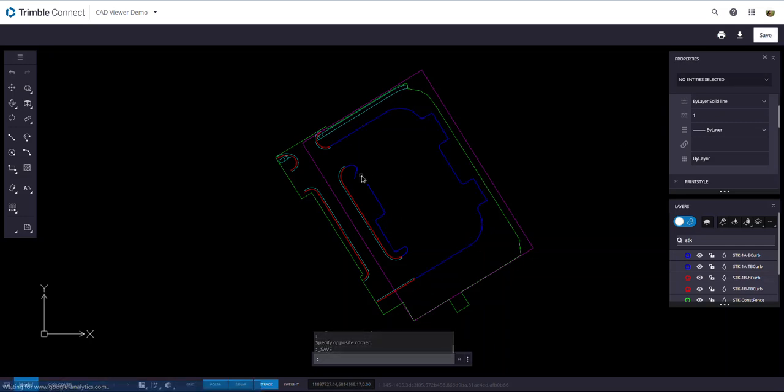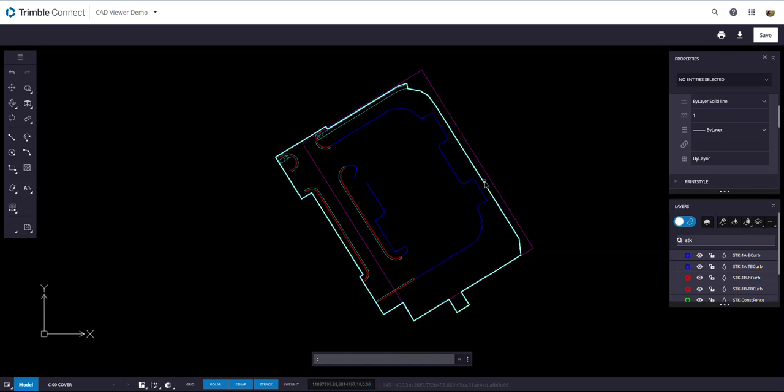And what we will work on next is bringing in some of the building pads and other interior grade break lines, concrete lines and pads that will eventually be staked out in the field as well. But this gives us at least some curb line to go stake out and some sidewalk to go stake out, lay out our construction fence, and know where our property boundaries are. So this is kind of the start of cleaning up the data in a 2D format.